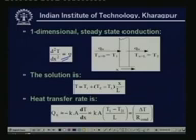and to solve this equation we need to know two boundary conditions, and this is the typical geometry. We have, let us say, a wall, a thin wall whose dimensions in y and z directions are much larger compared to the dimensions in the x direction, and here we have two boundary conditions where x is 0, that means we have temperature equal to T1, and x is L, that means the thickness of the plate is L, at x is L the temperature is T2. So these are the two boundary conditions, and this is the governing equation d square T by dx square.